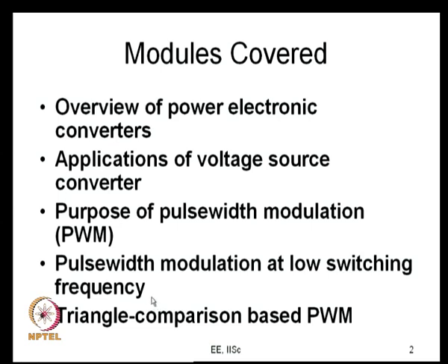We looked at single switching angle. With one switching angle we could control the fundamental voltage. With two switching angles we learned how exactly to handle the fundamental, how to maintain the fundamental voltage and also handle the harmonic voltages.